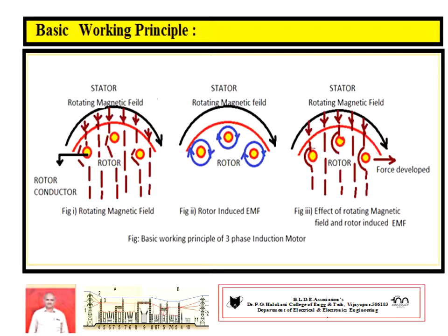Hence, the current carrying conductors are placed inside the magnetic field. A torque is developed, a force is developed, and the rotor starts to rotate in the same direction as the rotating magnetic field. It tries to catch up, and the rotor starts rotating. This is known as the rotor speed of the motor. It is also referred to as motor speed, denoted n RPM. It never catches the synchronous speed Ns of the rotating magnetic field.